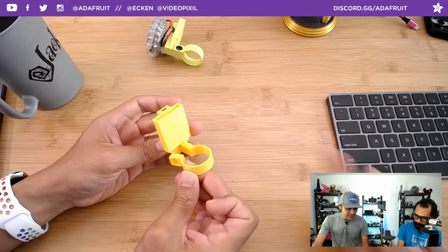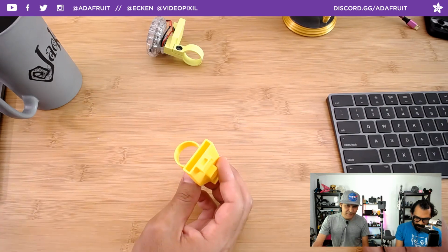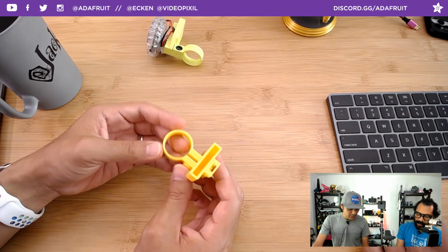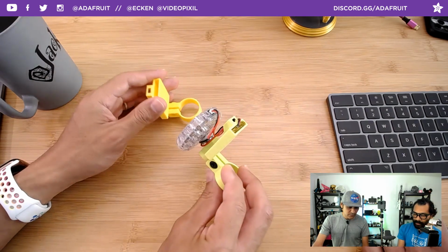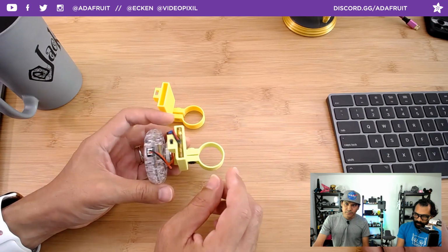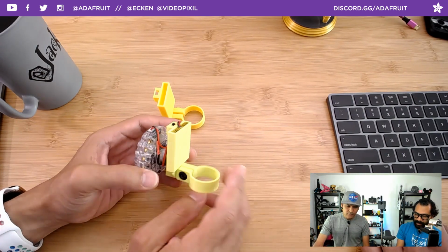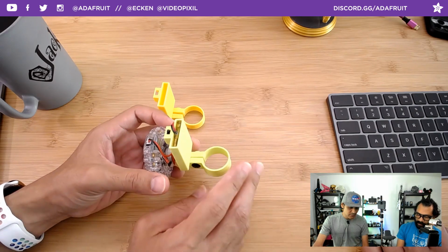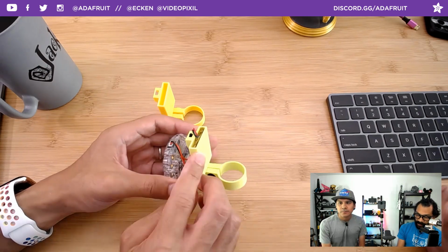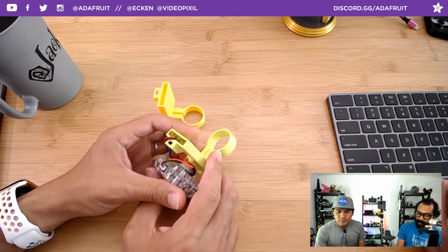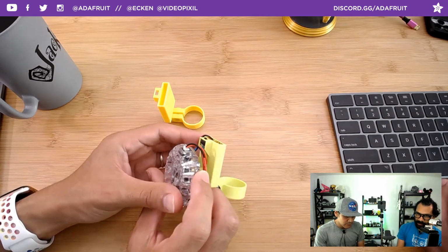So this little doohickey here, is it a two-piece or a one-piece? No, it's all one piece. This attaches to the seat post. I think it's called the post. And you can adjust the diameters for that. We're using an M5 screw to attach it. And then a really good idea that Dylan had was adding this nice little pocket that is built into the entire mount, so you can have this little pocket slide in there. We usually do this with NinjaFlex, but it works excellent with just regular PLA. And then he had a slide switch, so I decided to incorporate it into the design itself.